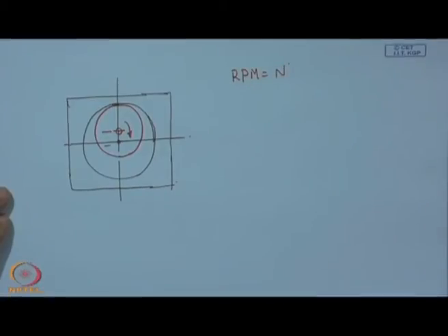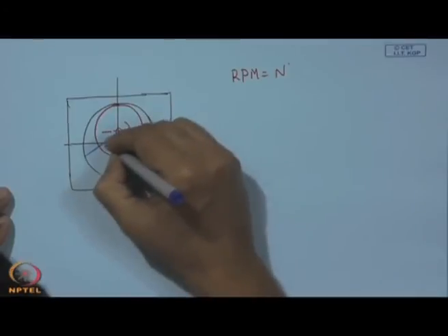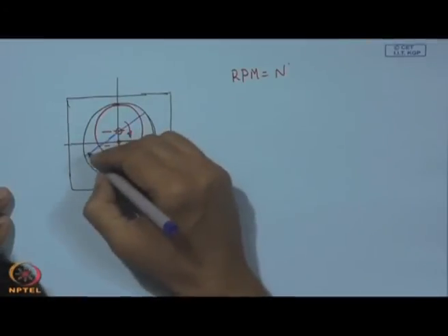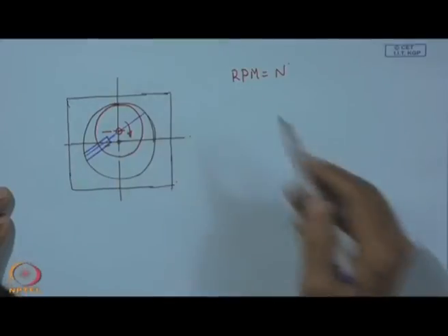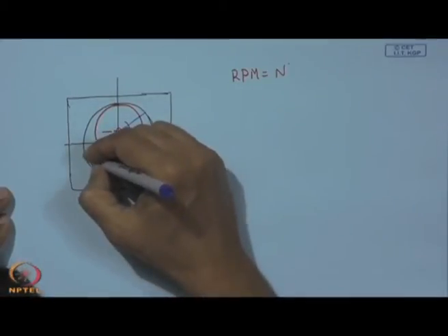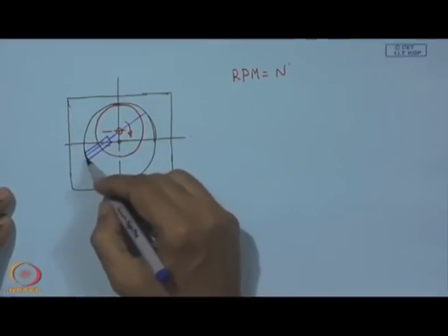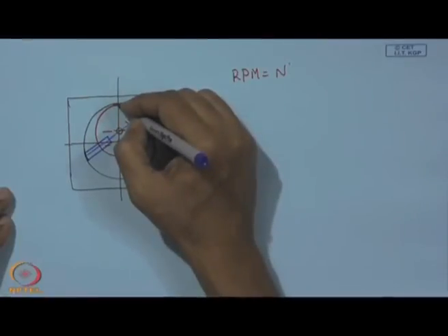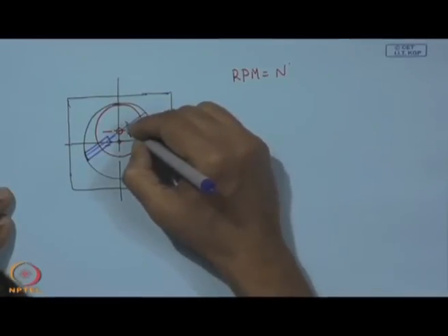Now, here we have two vanes, rotary vanes. So, through this we can have the axis, and here we can put a slot. This is one vane, and it is matching with this circular arc of the stator. So, that means it is in bodily contact. Here also we do not have much clearance, so it is also virtually in contact. So, we have another vane on this side.